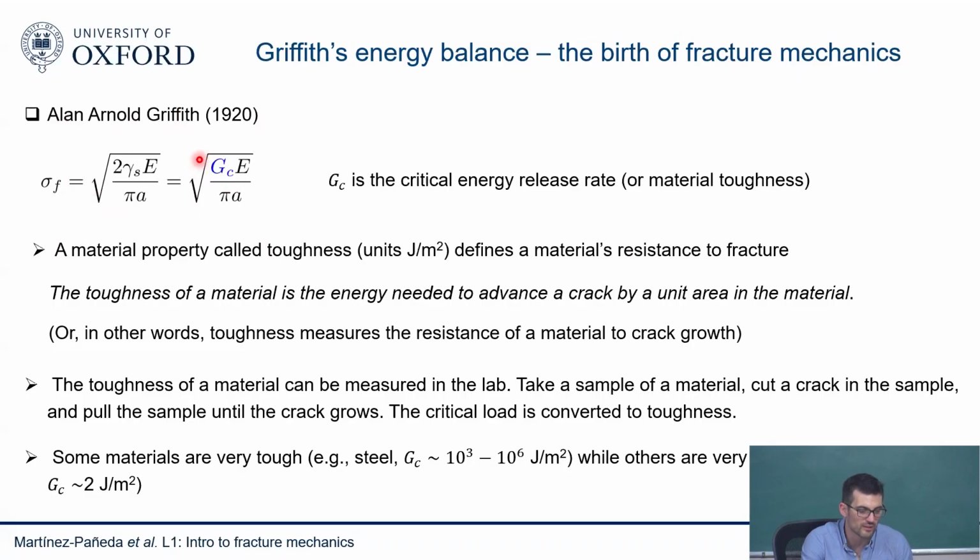And I think the only thing that goes beyond Griffith is that Griffith was focused on validating his theory. He was looking into metal fatigue, so he was looking at a wide range of materials, but he was validating his theory with glass, so he could compare surface energies, fracture energies, with theoretical estimates for ideally brittle materials, looking at really atomic separation strength. Some materials are very brittle, like silica glass, and they have toughnesses of a few joules per square meter.